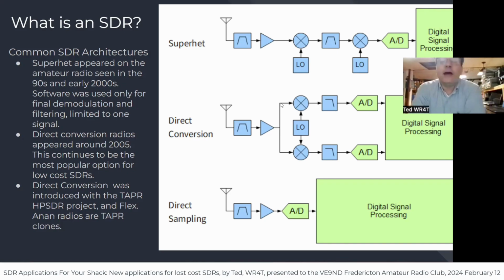At the top of this diagram, you see what looks like a traditional superhet receiver. This is a dual-conversion superhet receiver with RF filtering in the front end. This block diagram only has one section of IF filtering, after your first IF, which is typically where your roofing filter is in a more modern radio. And then your second conversion into your second IF. In a traditional radio, this is where you'd have a lot of additional crystal filters, and then your product detector. Of course, this will all be wrapped up in an AGC loop.